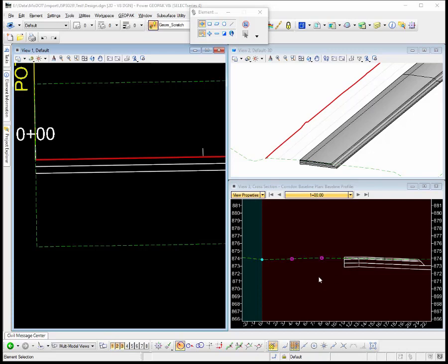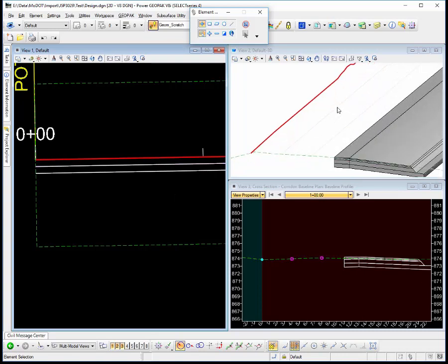So there's a couple of ways that we can do this, one more efficient than the other. In this first example, I'm actually setting point controls on these two lines, and so I have an alignment called EX1 and I have an alignment called EX2. On each of these alignments, I have assigned the existing ground as the profile to dictate that vertical information, and so you'll see these gray lines here that represents the 4 and the 8 foot where the profile is set by the ground.